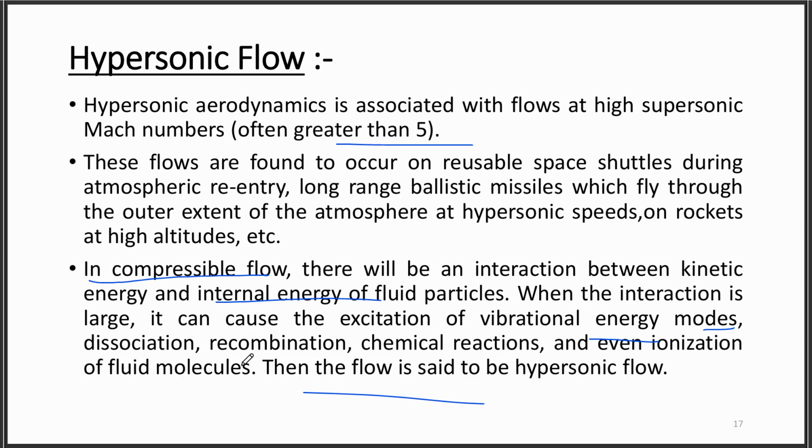When the Mach number is sufficiently large, the kinetic energy can be converted to internal energy of the fluid particle, and other modes of energy can be excited, which are vibrational energy, dissociation, and recombination. There can be chemical reactions also, and ionizations also. If all these things are happening, then the flow can be said to be hypersonic flow.